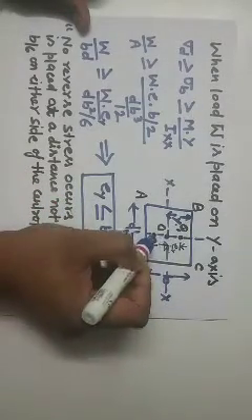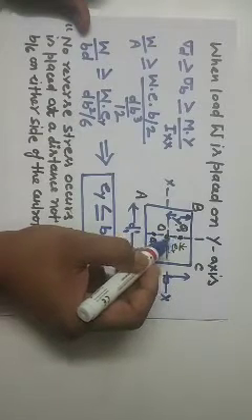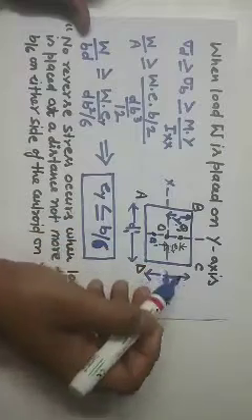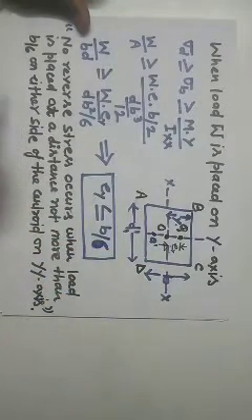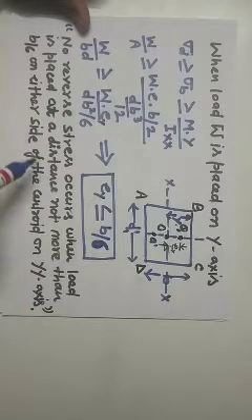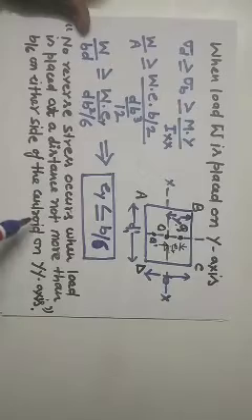So these are the 2 points here. This distance is y equal to b by 6, and this distance is also equal to b by 6. The same result will be there. Then what will be the conclusion? The conclusion is that no reverse stresses occur when load is applied at a distance not more than b by 6 on either side of the centroid on the y-axis.